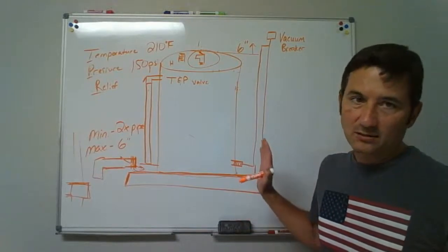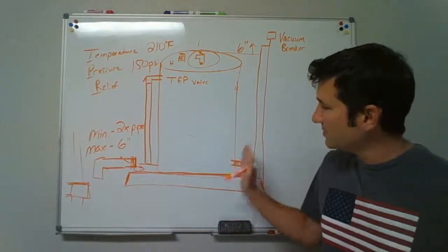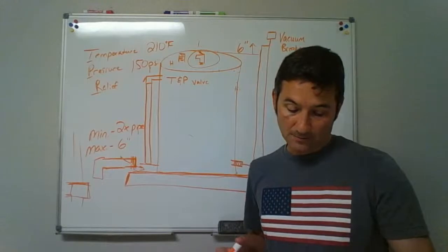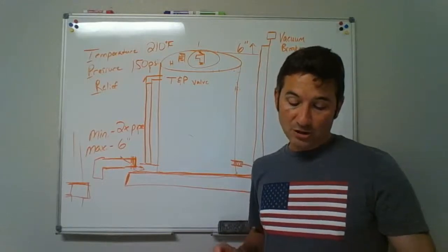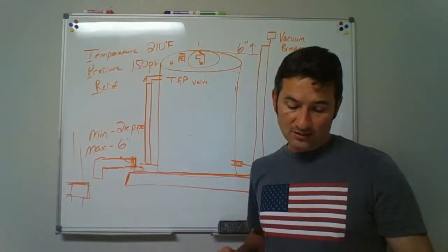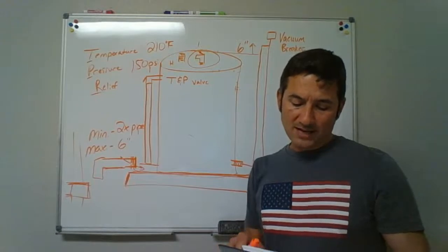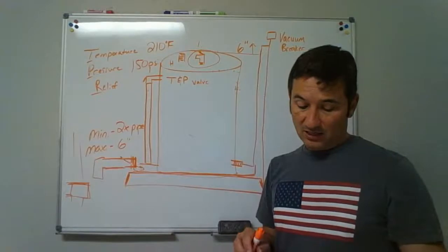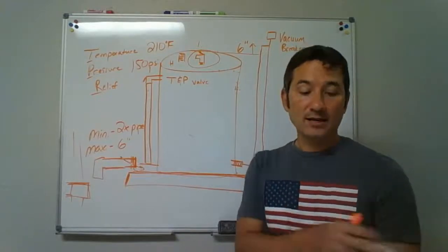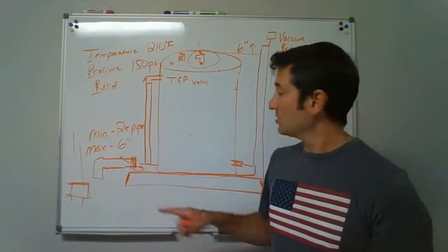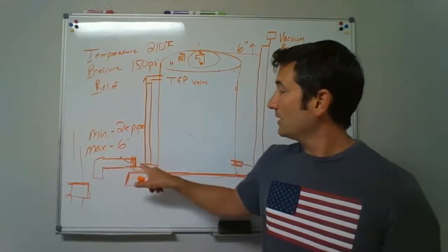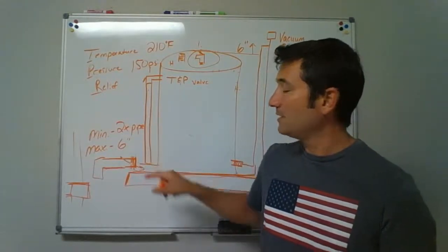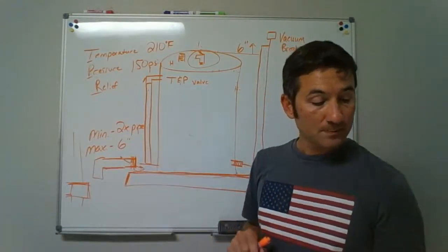Okay, all fittings, anything else that might be leaking around this water heater is going to drip into the pan. The pan shall not be obstructed by the appliance. The pan should be drained by an indirect waste pipe, having a diameter of not less than 1 inch. So the smallest size water heater drain for the pan is 1 inch.